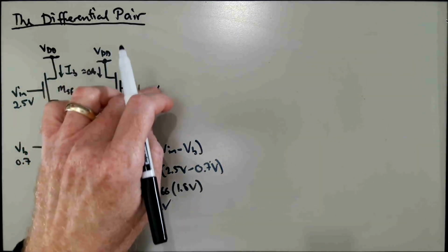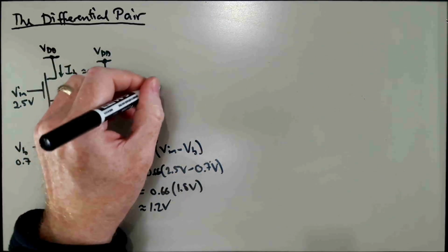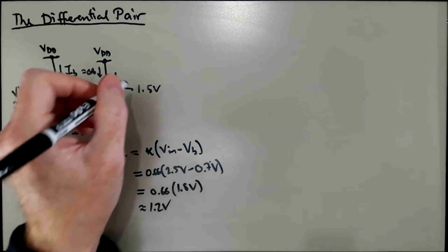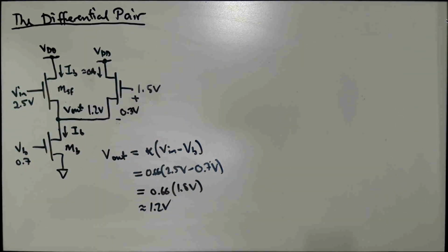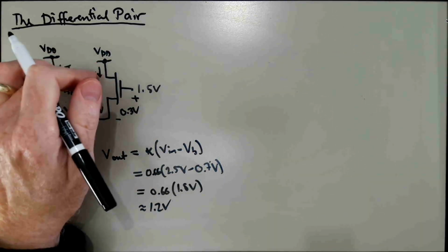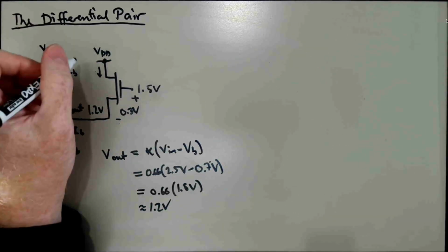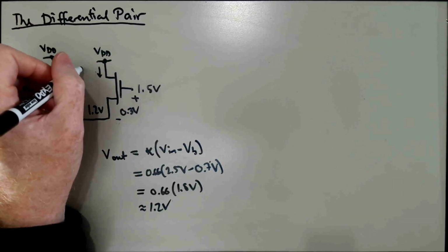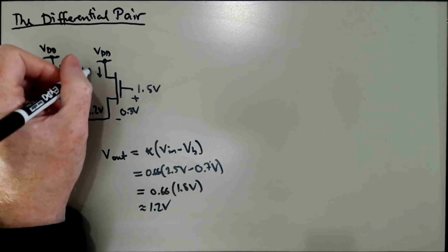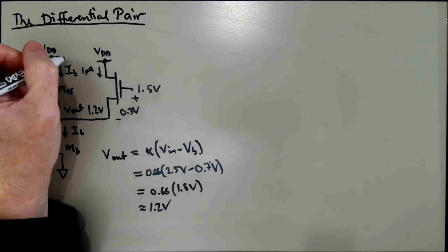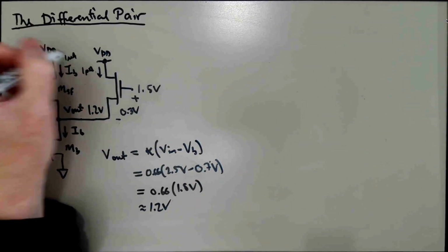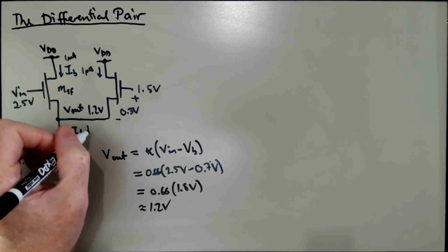I mean, suppose I make it 1.5 volts on the gate. Well, then we got 0.3 volts gate to source voltage here. How much current flows in the transistor with 0.3 volts gate to source voltage? Maybe we're up from femtoamps up to maybe a few picoamps. Still very, very small compared to the roughly, let's say, 1 microamp of current that we would have at threshold.